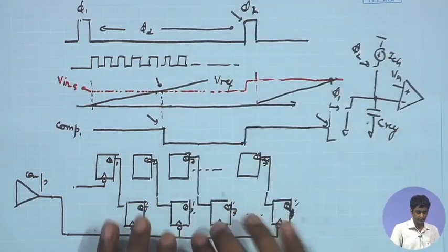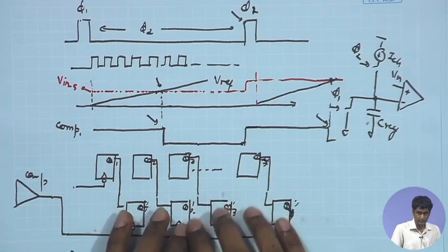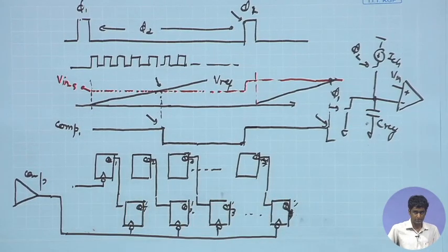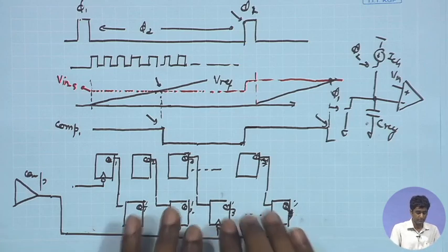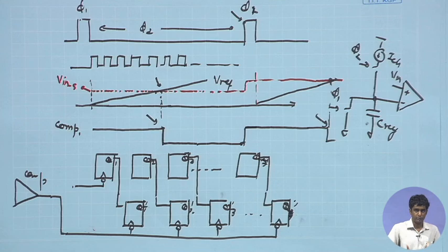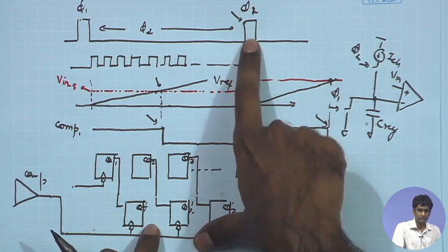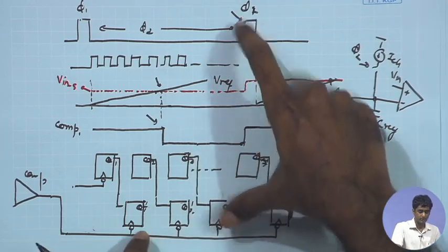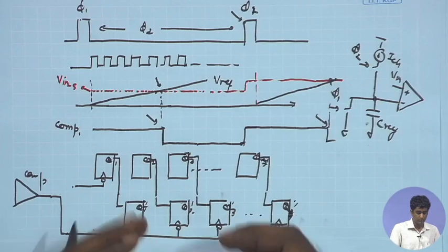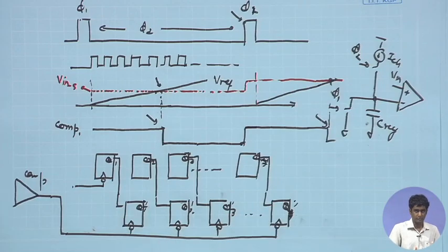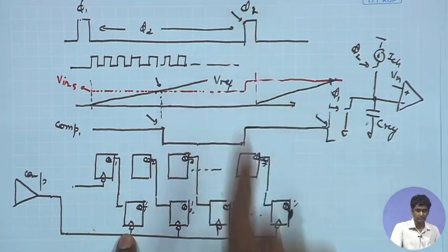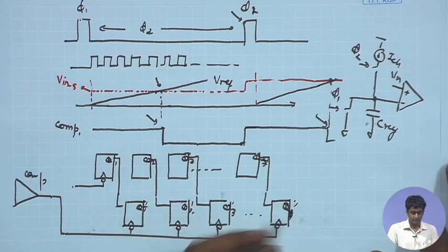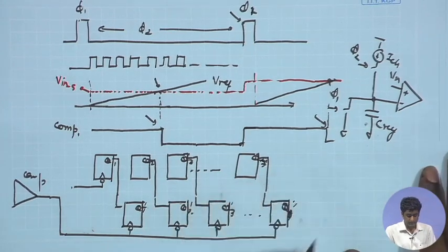So, before that I can take this data stored in this register, these 7 bits, into my digital domain. You will have another set of registers, or some logic blocks in the digital domain, which are going to use this data and process it further. Those digital blocks can be triggered with the positive edge of the clock over here, and they will take the new output, the new digital word corresponding to the last conversion cycle, say at the positive edge of phi 1. So, the overall ADC output